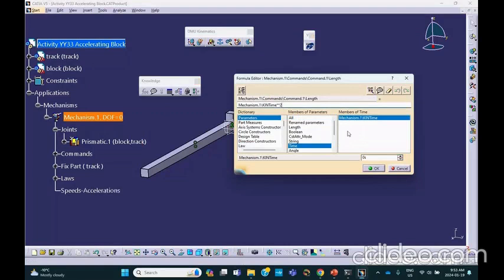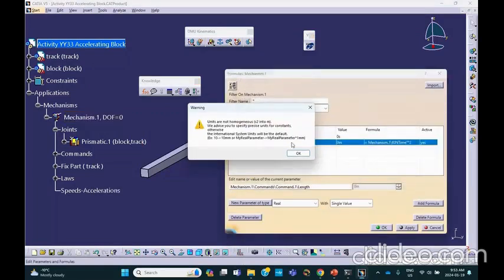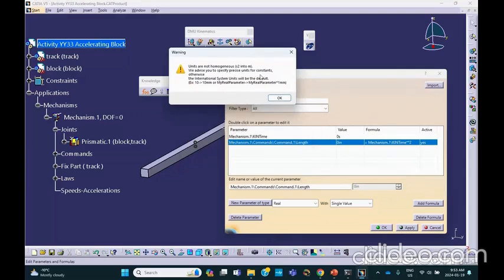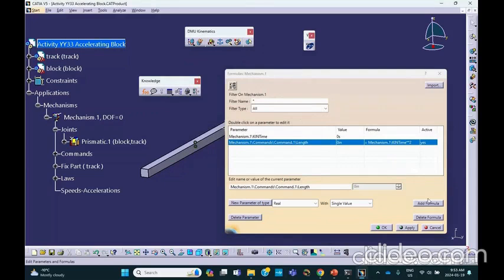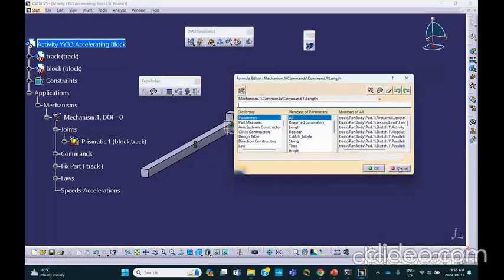However, it's the wrong physics. You'll see that because it's going to come back and say, wait a minute, your left side of that equation is meters or inches. The right side is second squared. These can't be correct. So let's fix that. We edit this. Oops, sorry, don't edit it. Double click on it. What we do is multiply this either in the front or at the end by 1 inch per second squared. So I can put it here, 1 inch underscore S. I think if we put S2 it will work, we'll find out.